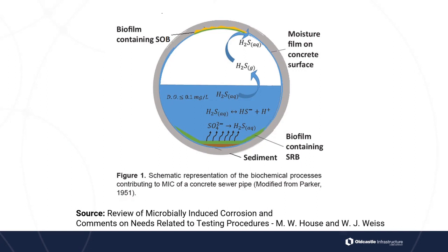All right. So the presence of these sulfur oxidizing microorganisms, or these SOBs, such as Thiobacillus thioparus, which is that first one that comes with a pH of about 9, doesn't necessarily imply an immediate risk of corrosion to the concrete. However, the presence of these organisms does indicate that there is a potential for further ecological succession of these bigger SOBs that are acidophilic, or more attracted to lower pH levels or more highly acidic situations, such as the Thiobacillus thiooxidans, and those are the ones that are associated, as I mentioned before, with severe corrosion.